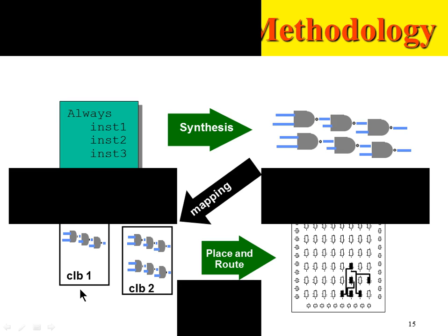Let's say I'm using a Xilinx FPGA. Under Xilinx FPGAs, there are multiple families and series of FPGA, let's say Spartan 6, Spartan 7, Virtex 6, Virtex 7, etc. Based on which FPGA you're choosing, there will be a technology library, which will have its own components. So this generic netlist will be converted to a technology specific netlist with its own components from the library.